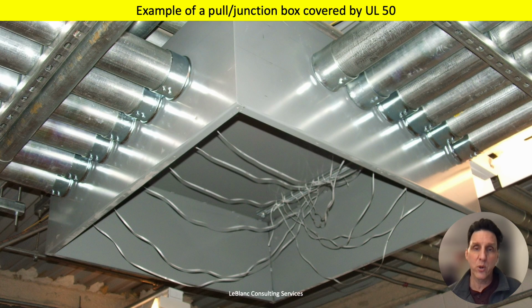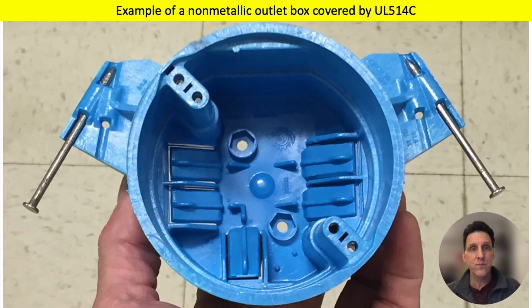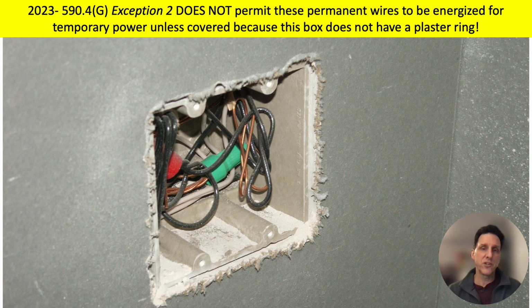All right, here's an example of a pull or a junction box covered by UL 50. I don't know anybody that calls that an outlet box. That is a junction box. And here's a metal outlet box covered by UL 514A. I don't think I would call that a junction box. Most people are going to call that an outlet box. Here's a non-metallic outlet box. And this is, again, covered by UL 514C. So we could debate, what's a junction box, what's an outlet box, because there are different product standards. But I think the intent is to include outlet boxes, even though it says junction boxes. So, splitting hairs, I guess.